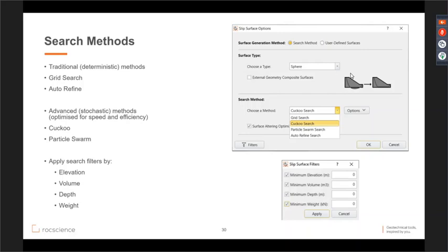So for slide 3, it's exactly the same as slide 2. What material properties for your rock mass, weak planes. If groundwater is affecting your stability analysis, you need to have that as an input as well.